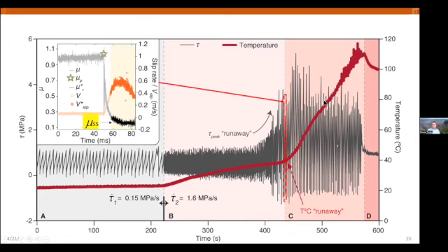So I guess it was one event where shear stress was 3.6. So one event like this one, for example, or this one. Yeah, this box here is not really centered around. I might have moved it. Anyway, you can see the velocity, how the velocity increases at the moment that the failure nucleates. The velocity goes pretty rapidly, in the order of 5 milliseconds, from 0 meters per second to 0.6 meters per second. And once it gets to the maximum, the friction fundamentally stabilizes around a value of 0.15. Okay, so mu SS is that value.